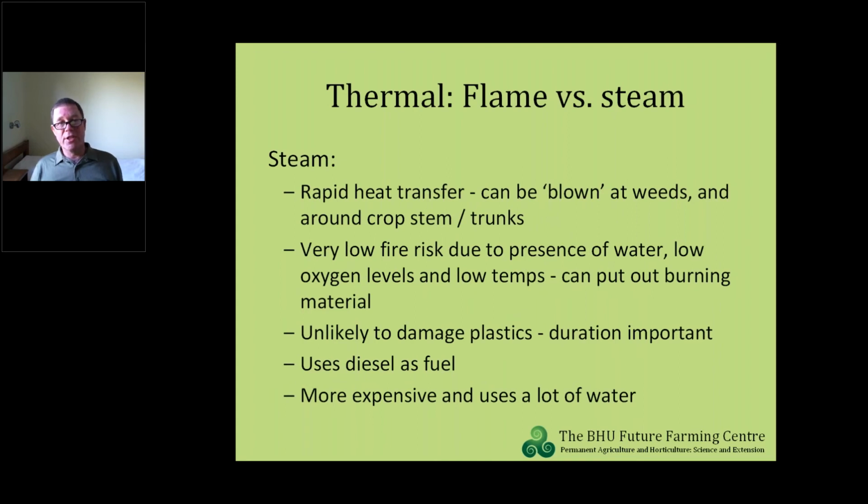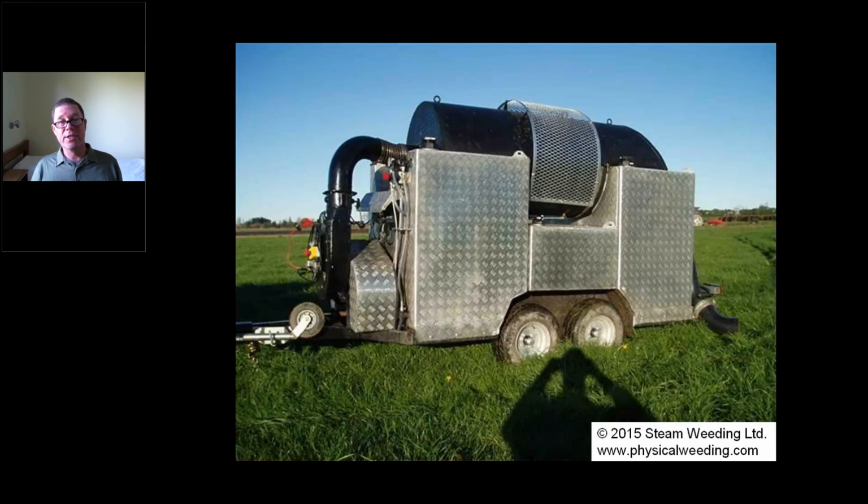Steam has the advantage that it uses the latent heat of condensation to transfer the energy to the weeds to heat them up. So you can literally fire the steam at the weeds. The heat transfer is almost instantaneous, so you don't need these big shields. It's a very low fire risk. Unless you keep firing the steam at plastic components for some time, they won't be damaged. And you can fill it up at the diesel tank just the same as the tractor, but they're more expensive and they use a lot of water. And I'll show you how much water in a second.